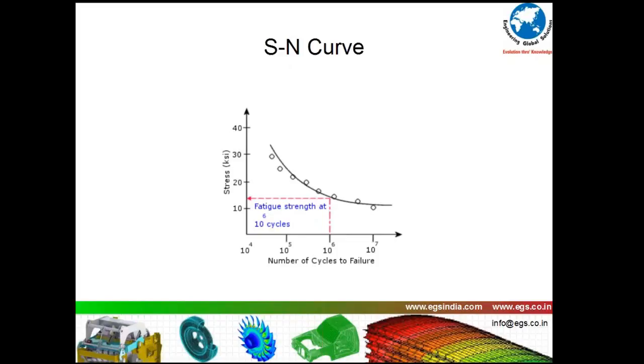Now please understand, the stress that we are talking about here is not the stress as you find in your finite element analysis. It is the stress as you find in your finite element analysis based on amplitude of loading, which is nothing but the stress range or the stress amplitude. There is a difference between the stress at a point and the stress amplitude. It is the cyclical load stress amplitude which dictates life.